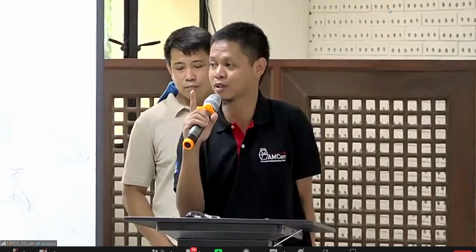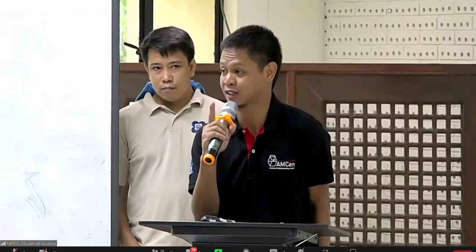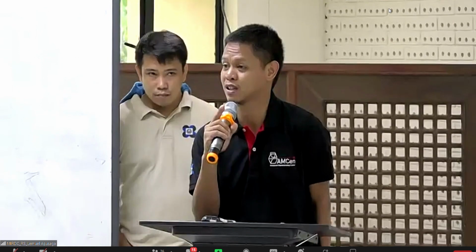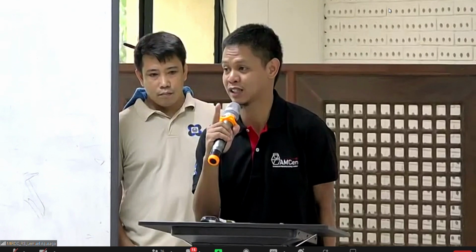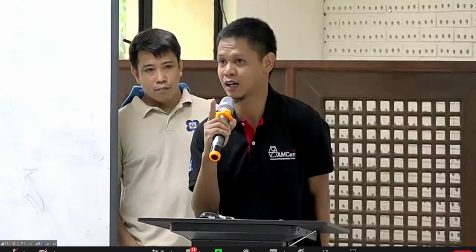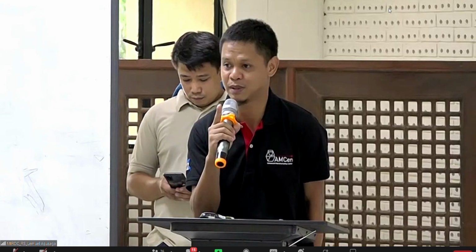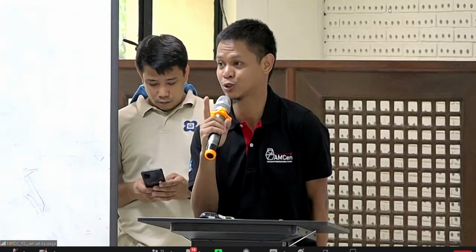What we've tried really is just PLA, because we've already seen some other people online doing it. They actually have a name for it already. It's lost PLA casting. So that's what we've tried. We're also planning to try out other materials if it burns off with the same quality, meaning if it burns off without residue, just as PLA does. Because if it works like that, we have the option of making bigger parts. Because PLA has a limitation in the size that it can make, because it might not be able to just hold its own shape owing to the limitations on its mechanical strength. So we'll also be trying to consider other materials such as ABS, ASA, PET, and use our bigger printers at the same time for us to be able to expand our capability, not just to PLA plastic.